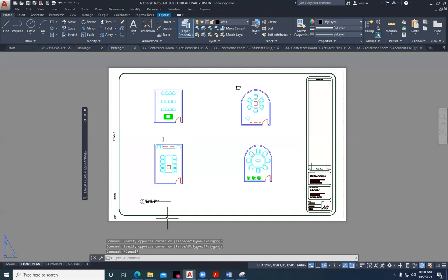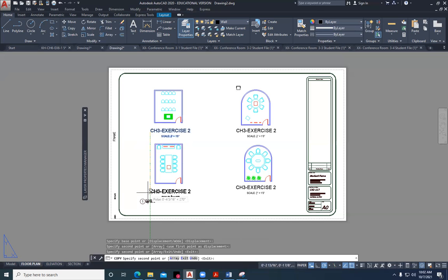And then I can select all of them. And then when you put the text on, you want to put the text on in paper space. So if I double click outside of the drawing, and it seems to be glitching a little bit, I'll type in PSPACE. That's the command. I don't have the newest computer here. If I want to put the text in, I can go with a multi-line text box. It's going to make that text 1/8 of an inch or 1/4 of an inch. Let's make this 1/8 of an inch and see if we can make that a 1/4. And I'll type in my information.